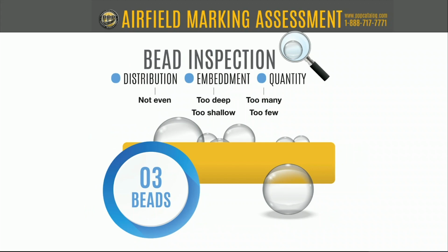I'd prefer to see 4, and really my ideal is 6. I'd like to see 6 paint guns, 6 bead guns, all ganged side by side, all painting in concert. That is a very difficult thing to do well. Very often we see that the material will start to overlap. The distribution will make the marking appear uneven, non-uniform. Again, probably two of the industry enemies, number 1A and 1B. Tough to do well.